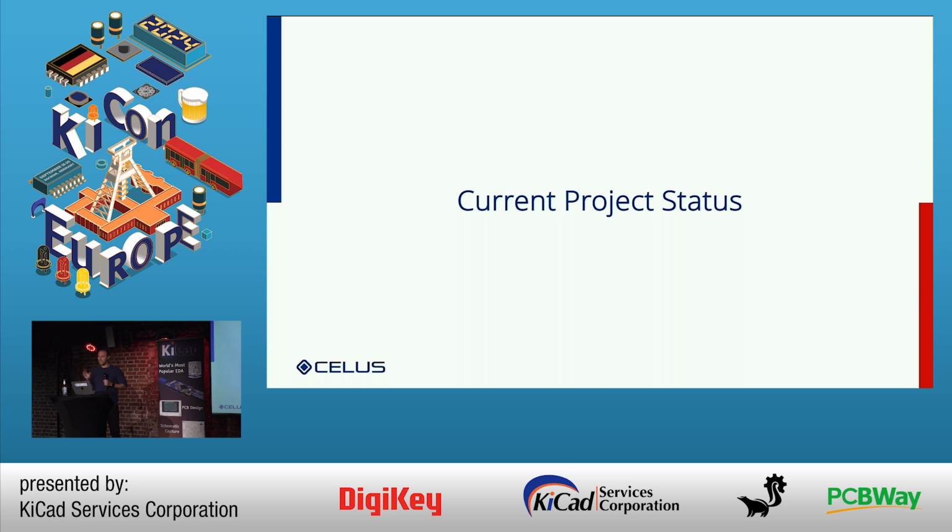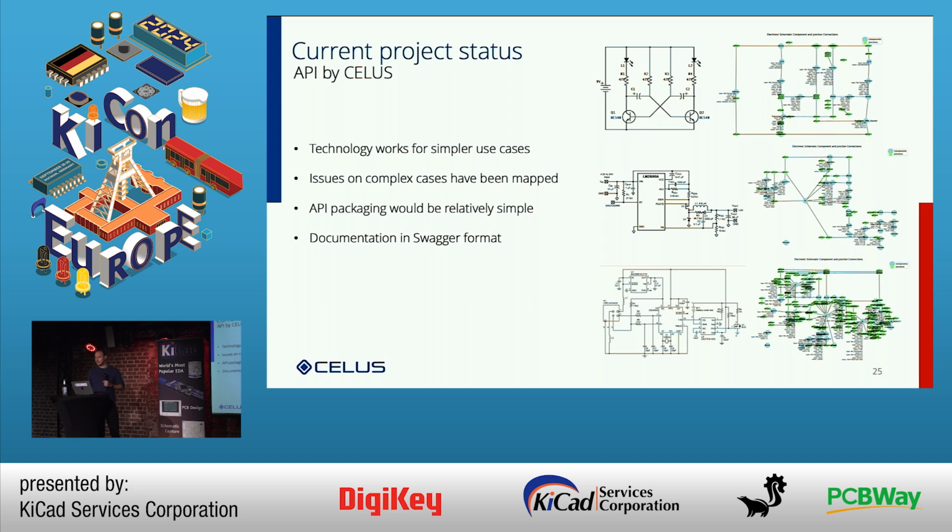Specifically for ICs, one thing that we identified is that we need to always create the symbol dynamically, because IC symbols are hardly something that you can map. The way that your symbol is drawn dictates a lot on how your schematic is going to look, and people may draw different types of symbols for the same type of IC. So we need to reproduce that as well if we want to keep some fidelity to the original image. But that is also possible to do.